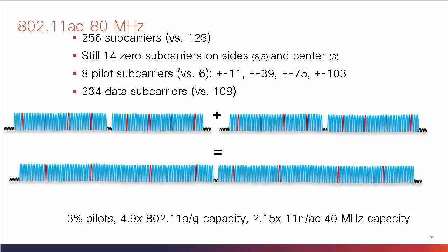So if you look at my light wave here, I know very well what the noise figure is around that red pilot in the neighborhood because I have the pilot to tell me and compare what I should receive with what I receive and know the noise figure for this area. But if I look right in the middle of my 80 MHz bottom half, I'm pretty far from the pilots at that area.